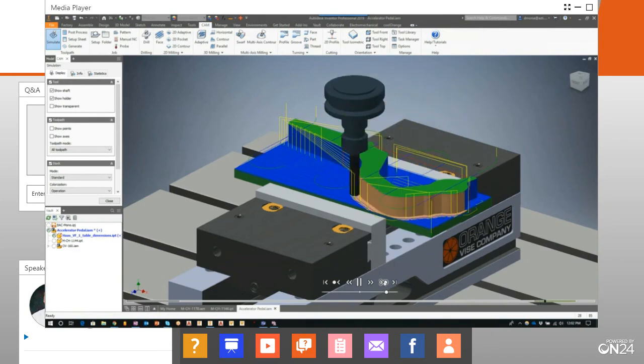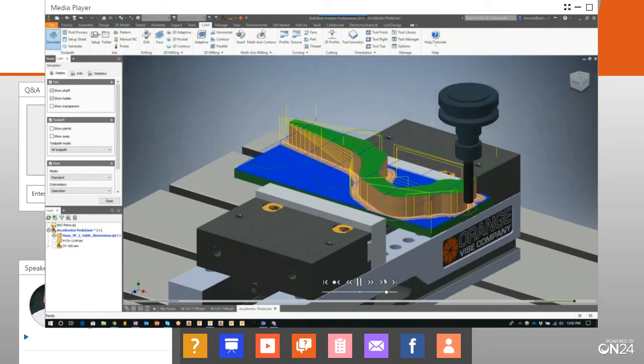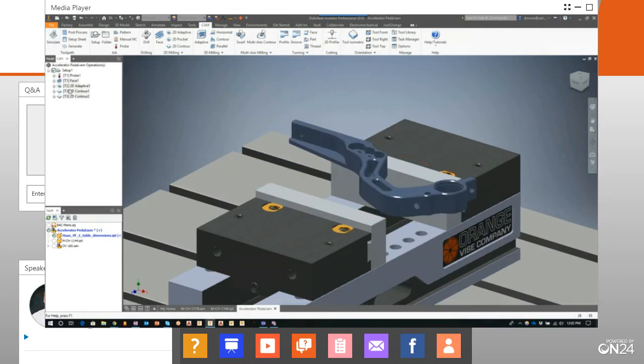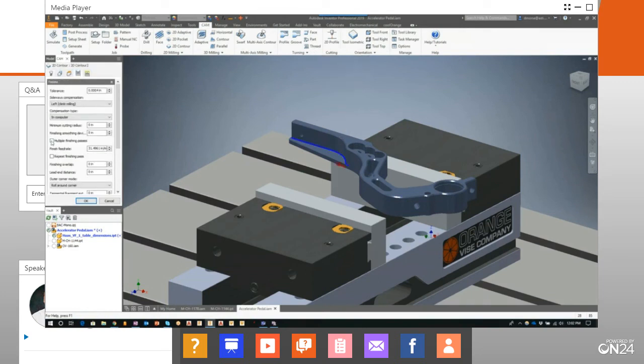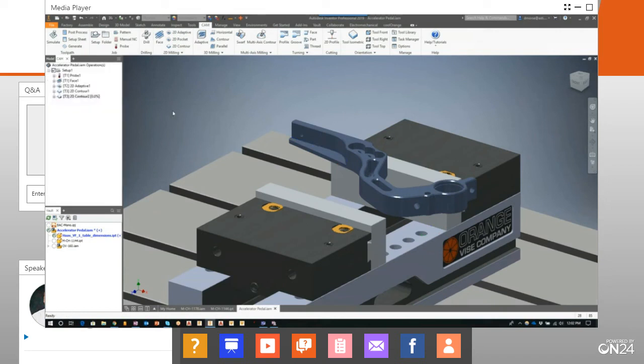Go to the next one, and here we got that finishing pass, and then we'll come in here and you can see that contour that we put in. That contour follows that path, but then it leaves some material. So I have full control over that tool. So I'm going to select the tool, right click and edit, and go to the passes. I'm going to say let's make some multiple passes, and we're going to try 4. I think 4 should work, but if it doesn't, we can go up from there.